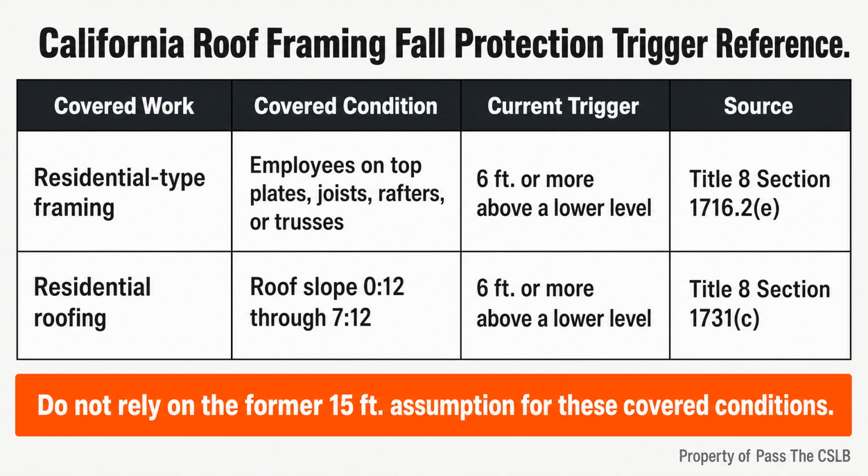What force is this member resisting? Is it in the correct third of the attic? Does its size, spacing, and connection match the approved requirement? Does the load path continue through the building? Those questions keep the framing discussion grounded in function instead of labels.